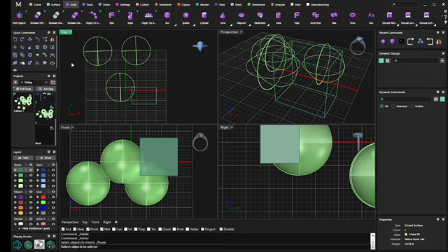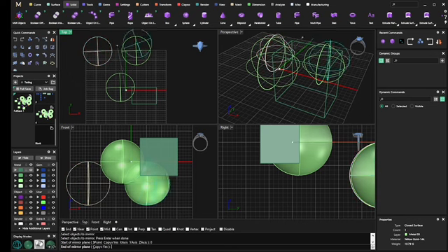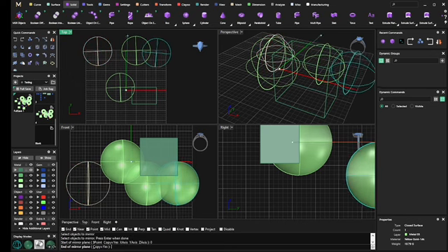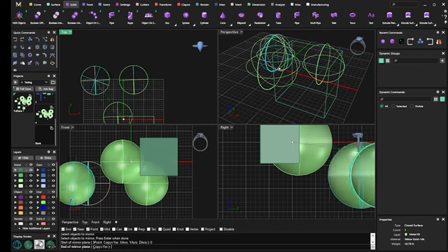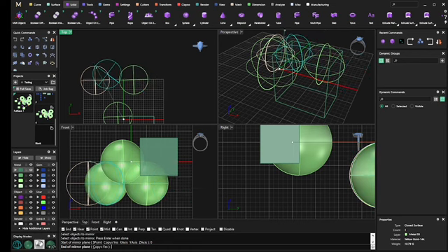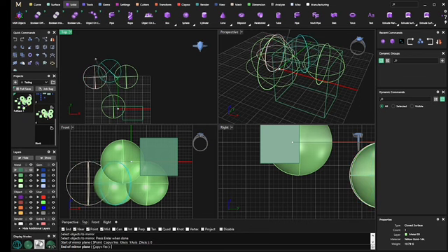Okay, so I right clicked on mirror. Select objects to mirror. I want to mirror this, and I want to press enter when done. And it already knows that I want to do it from my center because I clicked F4. Or I didn't click F4, but I right clicked on my mirror, which does it from F4, which is the center of your universe in CAD.